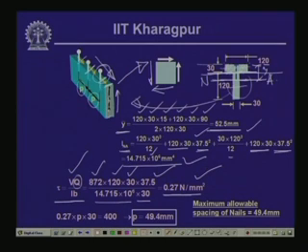Now, if these nails are spaced p millimeter apart, and I consider this particular nail, it has an influence area of half of this length and half of this length. So, this much length multiplied by the width, which is 30, that is 30 multiplied by p. That area multiplied by the shearing stress acting at that interface gives the force that this nail can withstand. Since a nail can withstand a maximum shear force of 400 Newton, if we equate to that, we get a value of p equal to 49.4 millimeter.